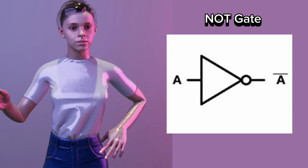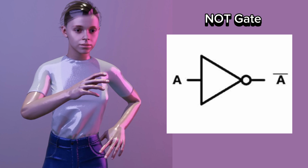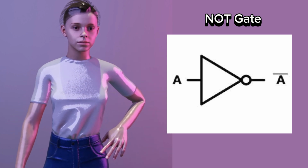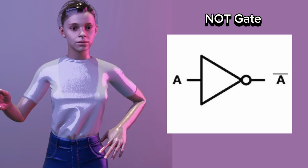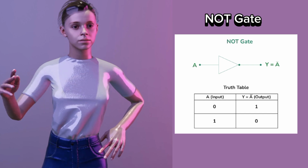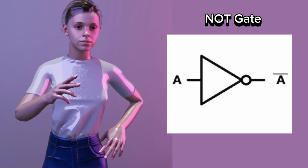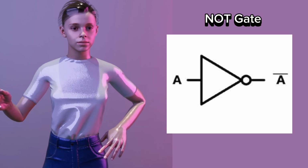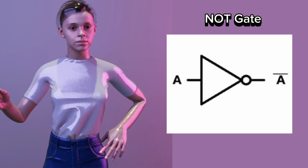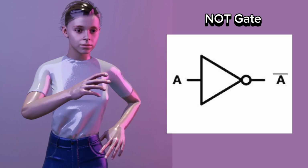1. NOT gate function. The NOT gate inverts the logic value of its input. If the input equals 1, true, the output equals 0, false. If the input equals 0, false, the output equals 1, true. Truth table. Input A: 0, 1. Output A': 1, 0. Symbol. The NOT gate is typically represented as a triangle with a small circle at its tip, indicating the inversion process. Application. Used to reverse logic conditions, such as in control logic circuits.